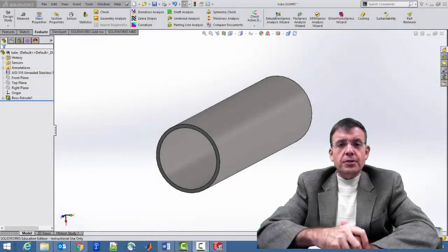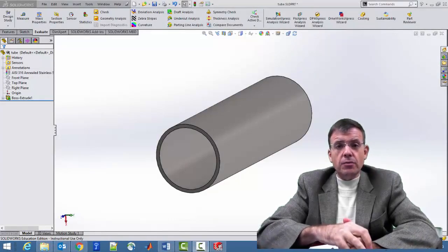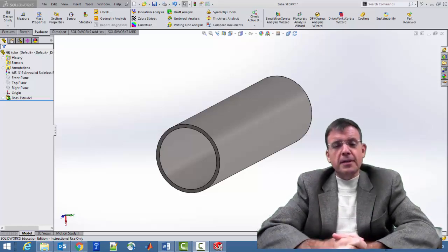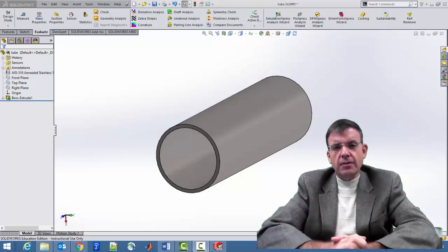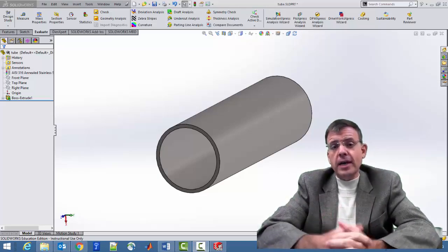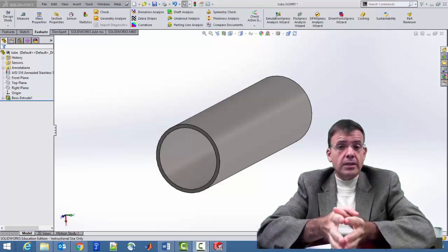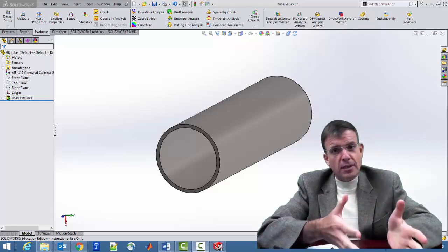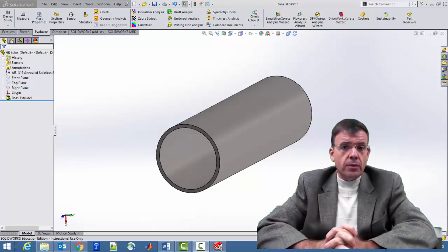Okay, let's now pursue a thermal example within the FEM capability in SolidWorks. This is going to simulate a curling iron. This will be a very, very coarse type of approximation, just enough to get a sense of how we can set up one of these problems, and to see the parallels between setting up these restraints and loads in the structural world and their equivalent in the thermal world.